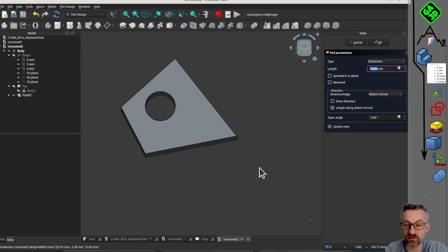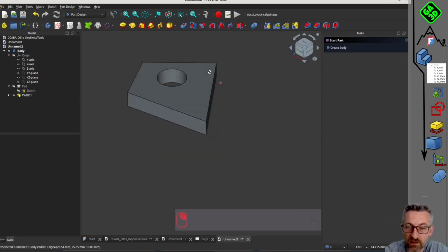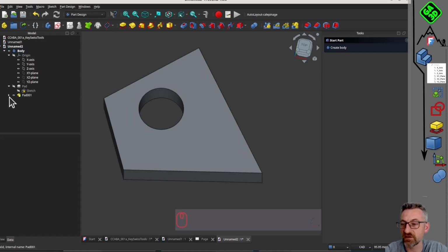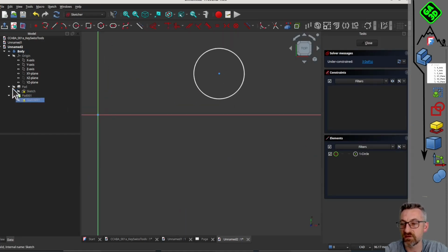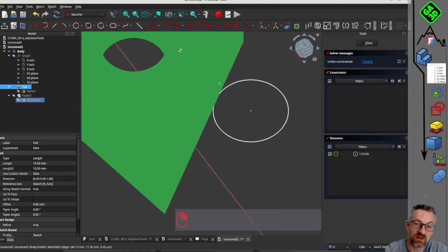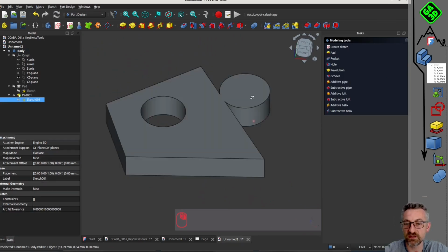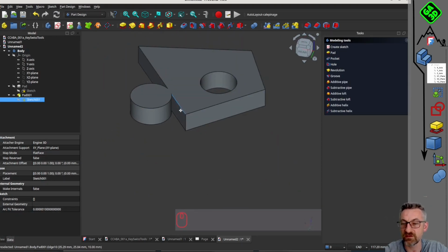Because with things like that, one day you'll find yourself with a part within a part that is not attached, or things like that. It's a bit dangerous. So, typically if I add a sketch here, and then I want to add an element just attached to my piece, but it's not interconnected. If you try to make an extrusion of the material, well, you see, nothing appears.